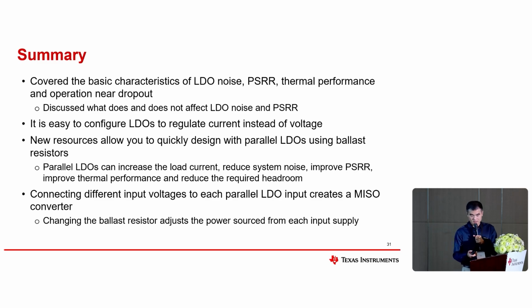So this is the summary. Today we talked about LDO basics and also the important specs for the LDO, noise, PSRR, and how to improve them. And then we talked about some advanced applications, including the parallel LDO, the constant current LDO, and also the multiple input and single output LDO application.